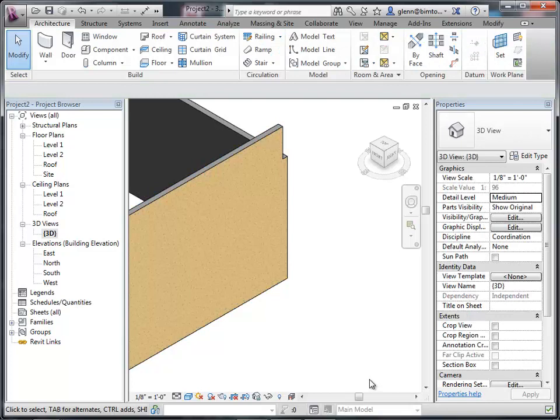So again, let me leave you with the notion that changing all these layers within a wall tends to actually be one of the more confusing things we can do in terms of setting this all up. We're going to give you some wall types that are already defined, so you can just pick them up and work with them. But I want you to know that you can customize these because as you're starting to model real construction assemblies, you get to the point where you really care about that level of detail, about how all the layers are fitting together.